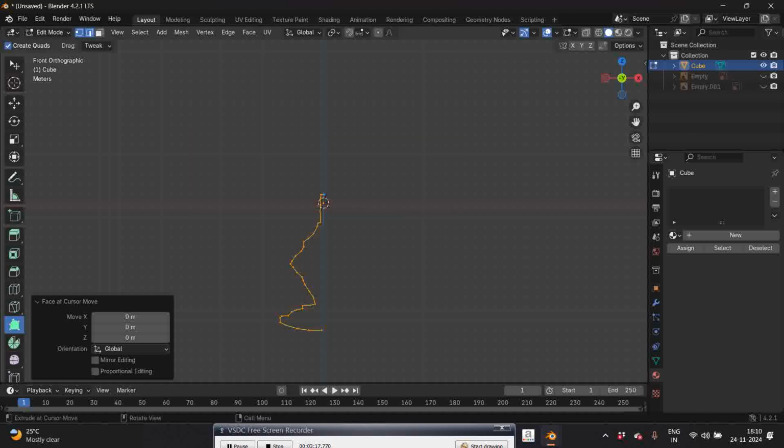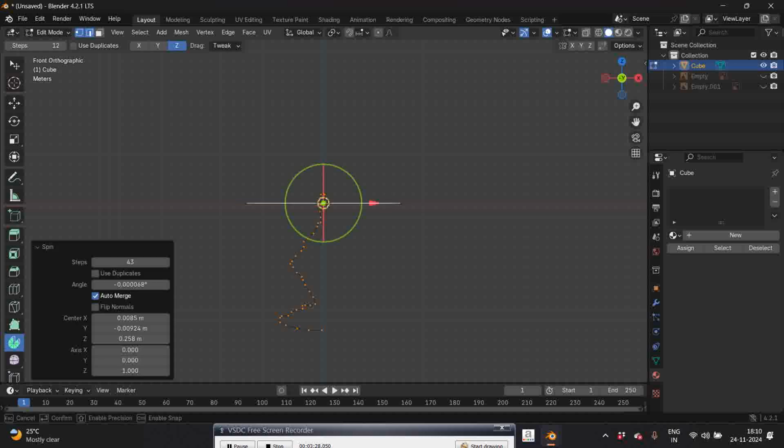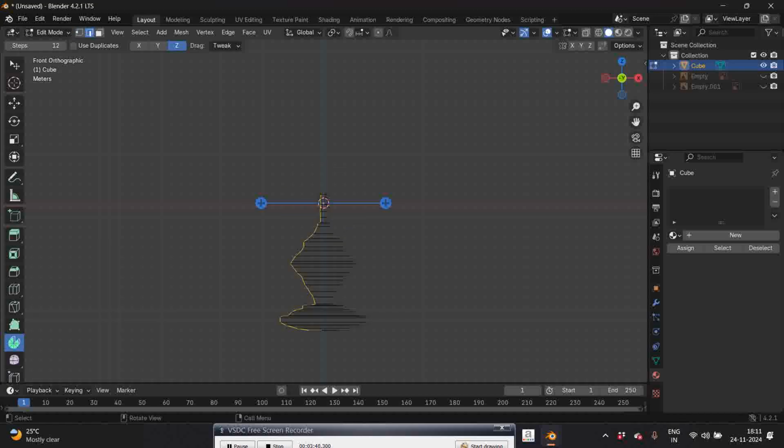As you hide it, you'll get these edges. I just need to click on the spin tool and rotate this 360 degrees. As this comes, you just type 360 on the keyboard, and you can see your vertices. Actually we have done this with the help of vertices. What I will do is take edges now, go back again and rotate again.